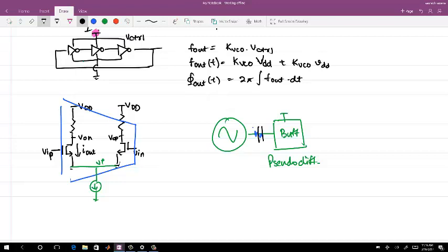You cannot rely on the common mode of the VCO, where the supply is regulated, and the buffers which are running on the full supply. You always have a common mode shifting there.